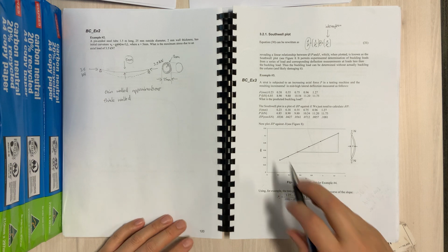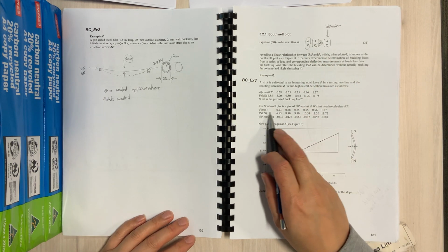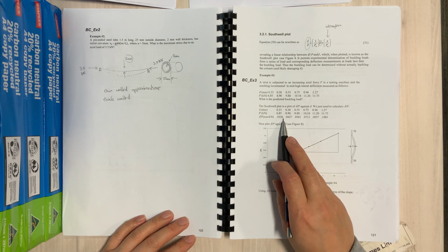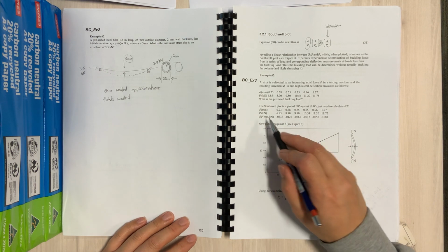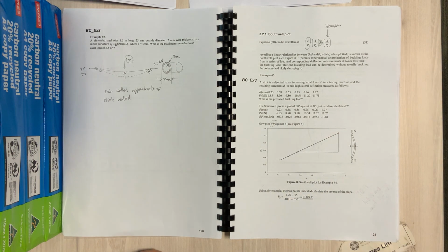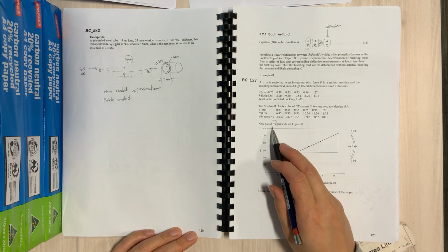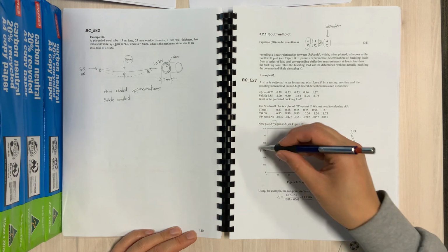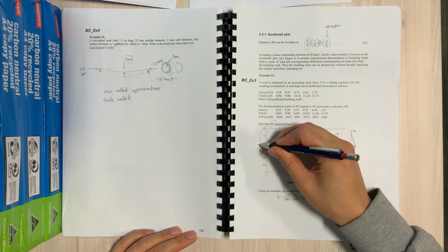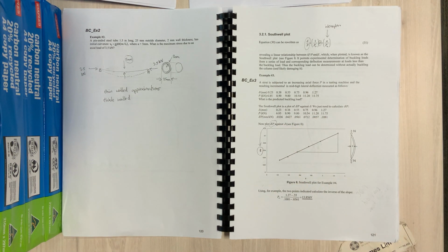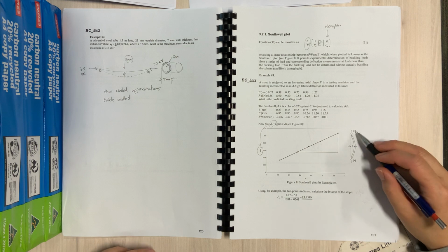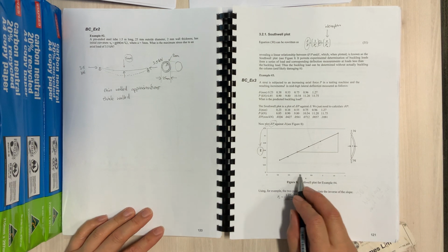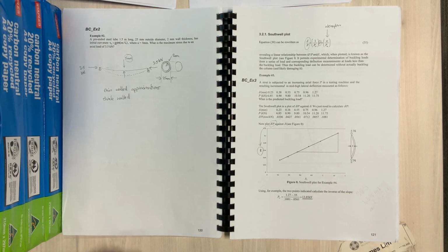So to do this, you just get these numbers and then you divide the delta by the P, and then you can tabulate that value there. That would be your delta over P, and then you would plot that on this axis going up here. So I know that says N, but N is also an axial load, which is shown here, so just replace N with P. And then you plot that against delta, which we see there.